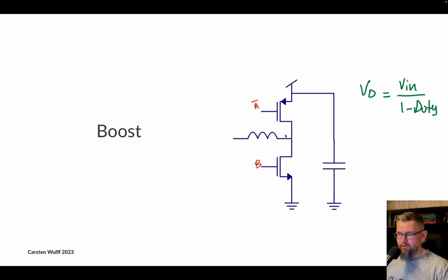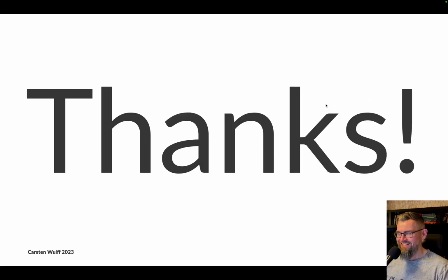You have the inductor, and then you set up the current by pulling the NMOS to ground, and then you deliver the current to the load through a PMOS. Same thing, but slightly different. Okay. There are also others. So you don't have to do it with inductors. You can do it with capacitors.